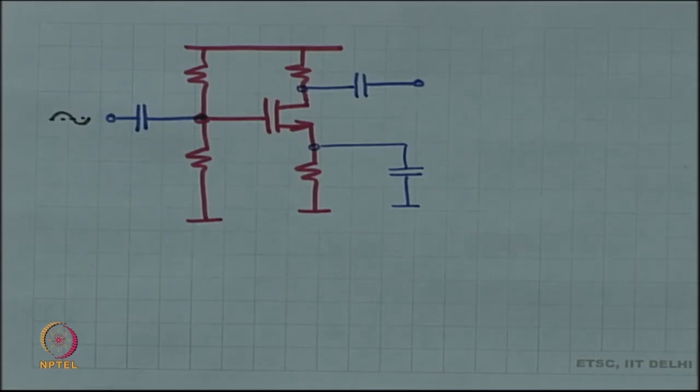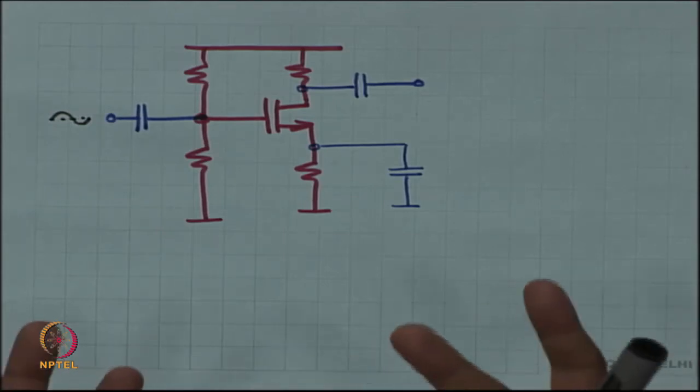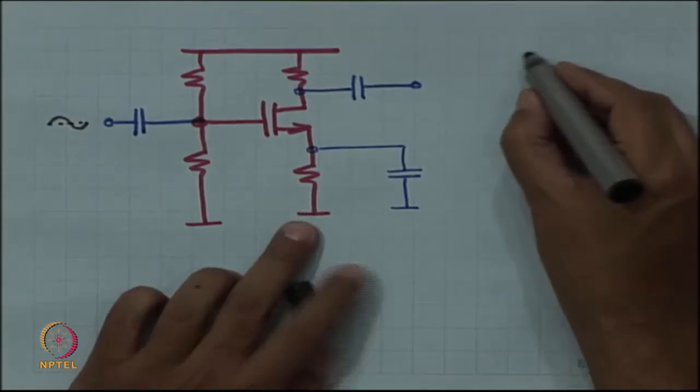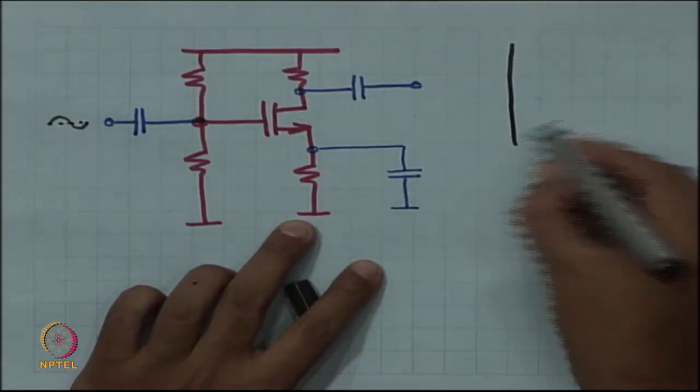Now, this MOSFET has to be kept in its flat region of operation, otherwise what? Otherwise, the basic understanding of the MOSFET, the gm for example, is no longer what it should have been. Okay. The MOSFET is no longer going to reside at the nice operating point that you had set.